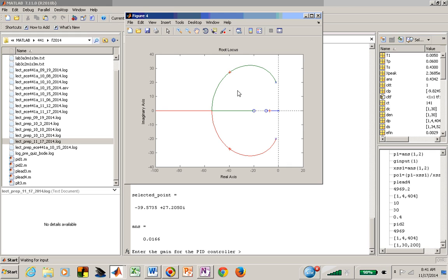And that's going to also influence my transient behavior. I now have a third pole. I have 2 zeros. So I have a 3-pole 2-zero system. All of those are obviously not a pure 2-pole system. So I have to take those formulas or those design specs with a little bit of hand waving.